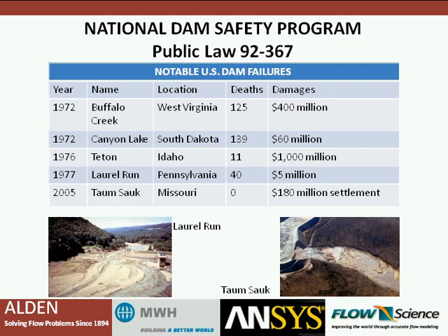More recently, there have been a series of failures that happened in the early and mid-70s that led to the passing of the National Dam Safety Act. And this was a program that resulted in the inspection of all non-federal dams, and really is what I'll call the impetus that led us to the modern era of dam safety. The program started in 1978, and dams were evaluated primarily for two factors, structural stability and spillway adequacy. There was a lot of rehab that was done as a result of those projects, and a lot of upgrades have been done over the years, but we're still not done with that yet.